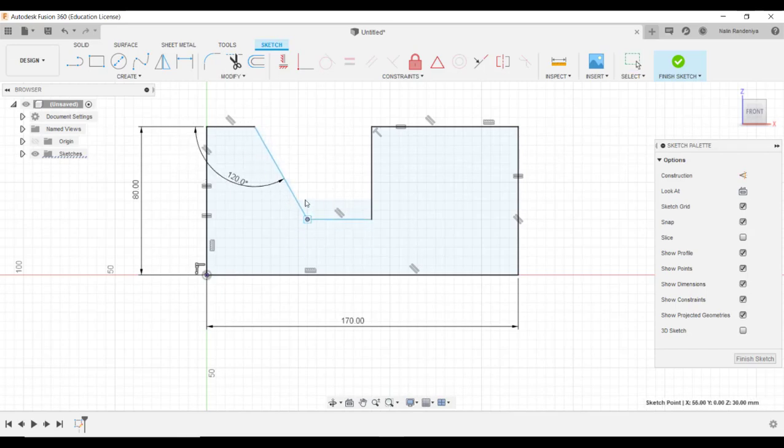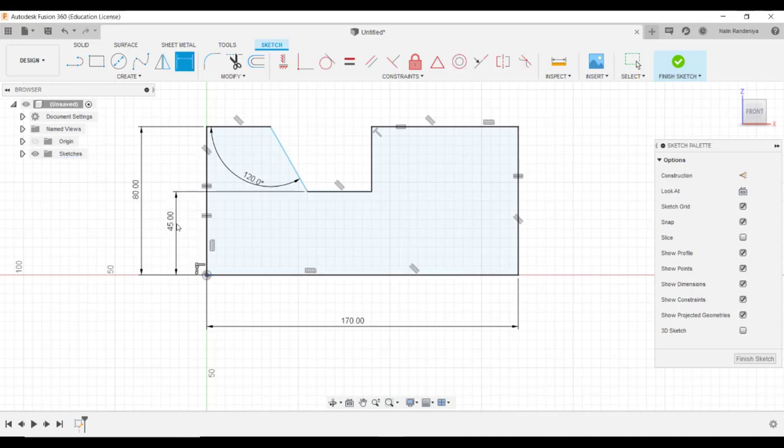It can also go further down as well. So if we give dimensions for this line, both horizontally and vertically, that should do. Let me go ahead, this line and this line, I would say 45. And one last thing, I can give dimensions to this point. Click and origin. I'm happy with 55. Press enter. There you go. So now we have a fully constrained sketch here, with the dimensions and constraints all placed in here. Okay, so that is how you create a fully constrained sketch.